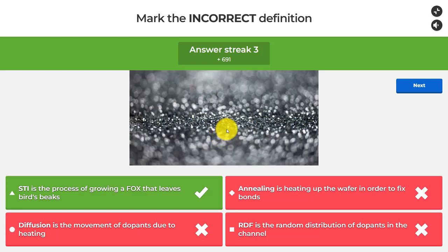And when we take some sort of a random, statistical process of shooting dopants into a channel at a certain depth, and we want to get some amount of dopants into there, that's not going to be exactly 100 or 95 dopants or however many we wanted. It's going to be a bit more or a bit less, and that bit more or a bit less can cause really hard fluctuations in our VT, and that is really the main cause of process variations in nanoscaled planar technologies.